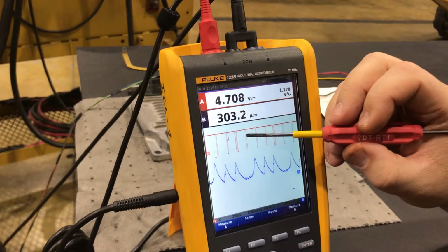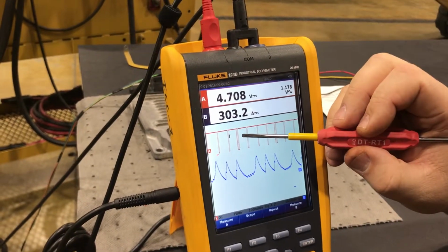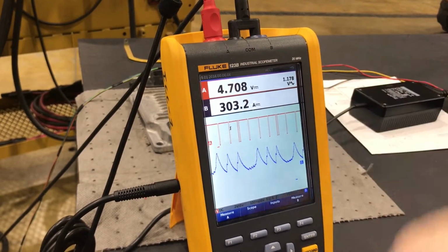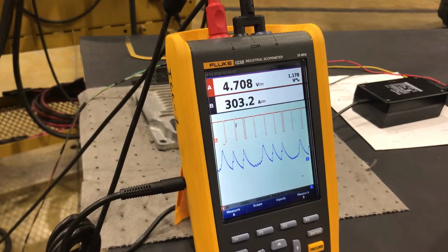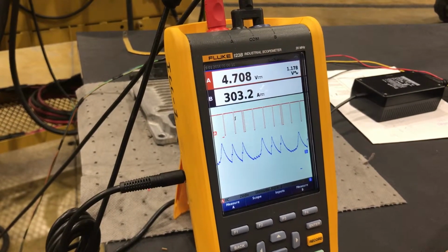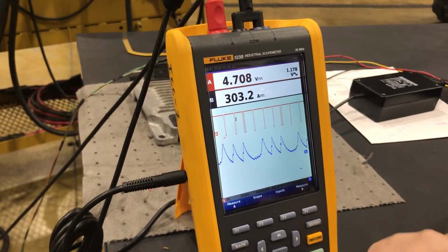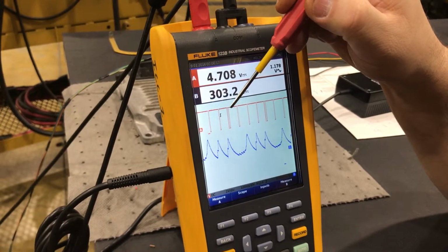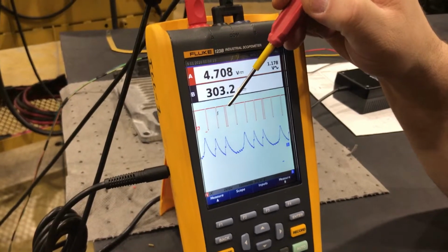So I've seen this quite a few times now. The question is, why would they not put this at TDC? Why would they put it before TDC? The simple answer to that question, logically, is I want to know before number 1 happens, not when number 1 happens. So they typically put the unique identifier on the cylinder before. And this would be at the end of the firing order.